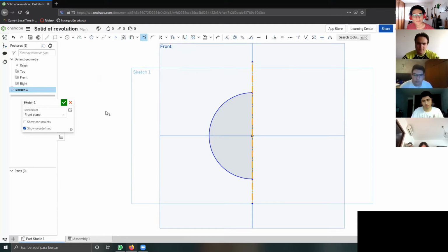Okay, thank you. Actually, I could do it with these halves here. I click here on construction, and now it's a construction circle. And to return it to normal, I click again, right click on construction, so it goes back to normal.